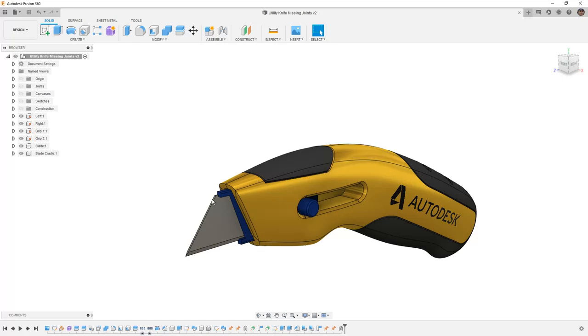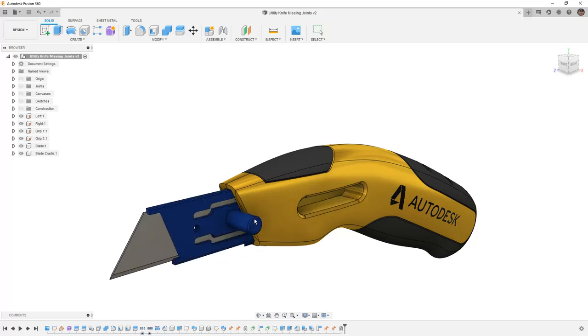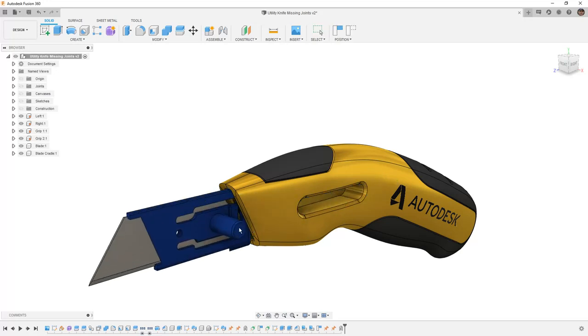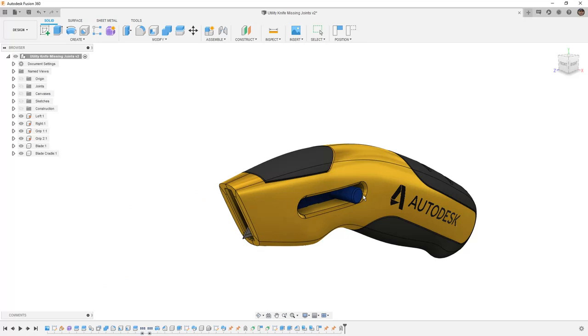We've applied our slider joint, and now our part is free to move about. In Fusion 360, we can grab onto the part and move it freely in the canvas, respecting all joints that have been applied. We can capture the position, and we can also revert it back to its original location.